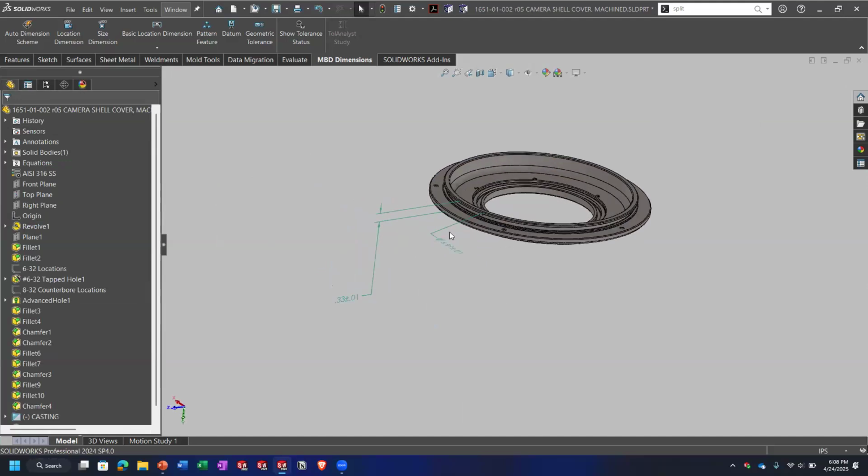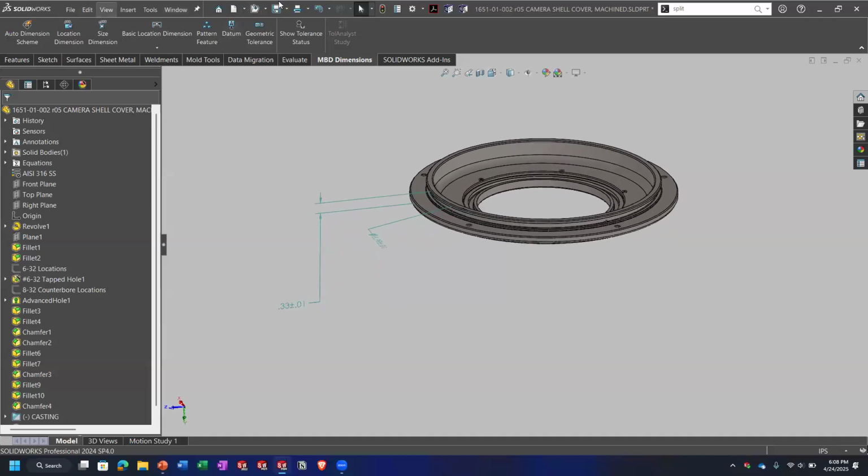Yep. So that allows me to move around things so that on that drawing, if I put on the right view, let's say the front view is way too congested, and I want more dimensions on the right view, I can go into the part, say, hey, move these 4 dimensions to the right view because it's a good dimension in either view. Then you can clean things up and have it look that way for you. Anyway, so I got those dimensions in here.